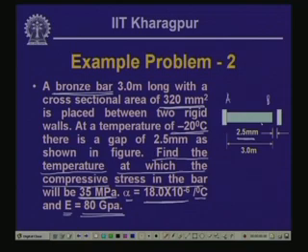Now, in such problems where we try to evaluate the stresses due to change in the temperature and where such restrictions are imposed, like the bar is fixed between the walls or the bar at this point is not allowed to go beyond a certain value, we try to first remove either partially or wholly the restrictions, and allow the bar to move freely due to change in the temperature.